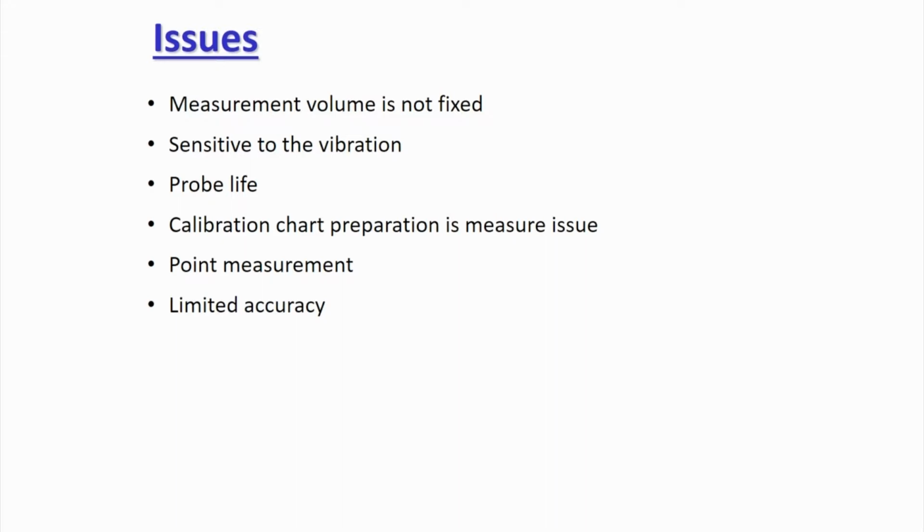So, generally we do it in two ways. First, you do either the gas and solid packed bed condition in case of gas solid, or you do pure gas and pure liquid in case of the bubble column, and you use the similar formula which we have discussed for the capacitance probe, and measure the solid concentration or discrete phase concentration or discrete phase volume fraction. Okay. You identify the phase from that, or you can use the capacitance probe to do that. Okay. So, generally some people also use, particularly for the gas solid system, the capacitance probe to identify the phases. Now, why is that needed for the gas solid system?